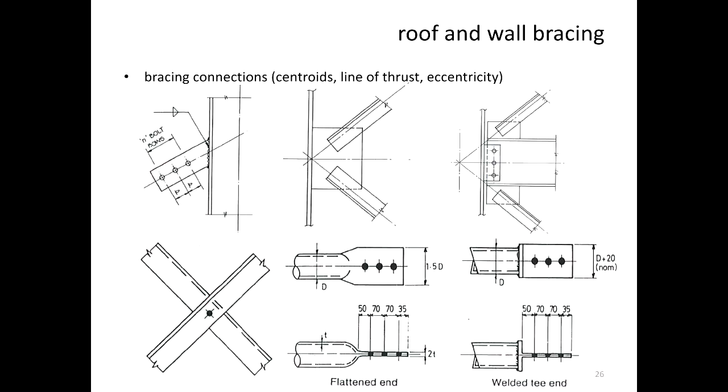So that is why, you see, this one, the force acting on that member goes this way. This one, the force acting on that member goes this way. And all of that should be built to perfection to ensure that the center of that cleat plate is where the two intersect exactly. So that eliminates eccentric load acting on the plates.